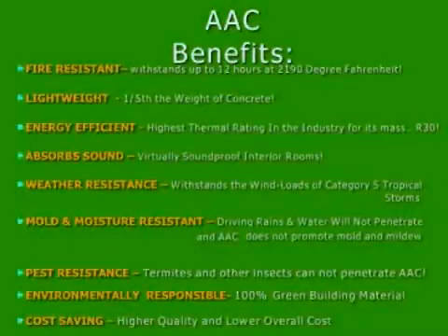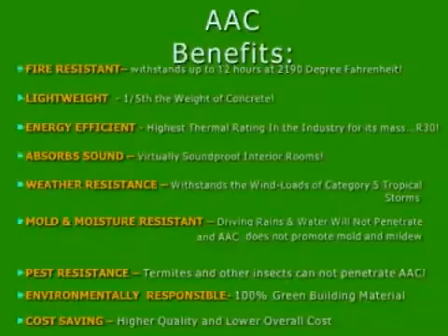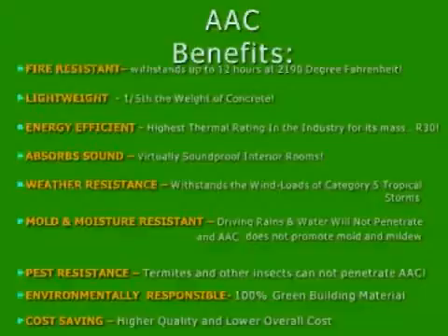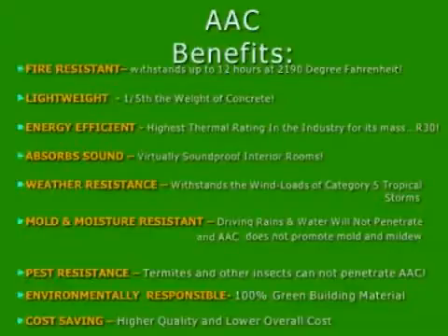Let me summarize all of our AAC benefits. Fire resistant: it withstands up to 12 hours at 2190 degrees Fahrenheit. Lightweight: AAC is 5 times lighter than concrete. Energy efficient: AAC has the highest thermal rating in the industry for its mass, up to R30. Absorbs sound: virtually soundproof interior rooms and to the outside.